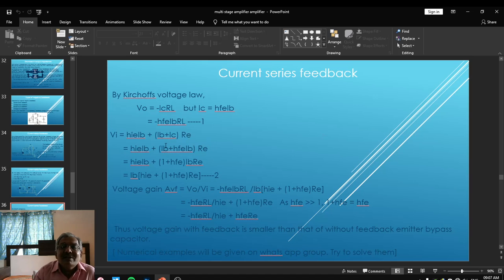Now take IB common from this bracket so as to get IB HIE plus 1 plus HFE into bracket IB RE. Now take IB common from this entire bracket so that IB into bracket HIE plus bracket 1 plus HFE into RE. Let me call this as equation number 2.